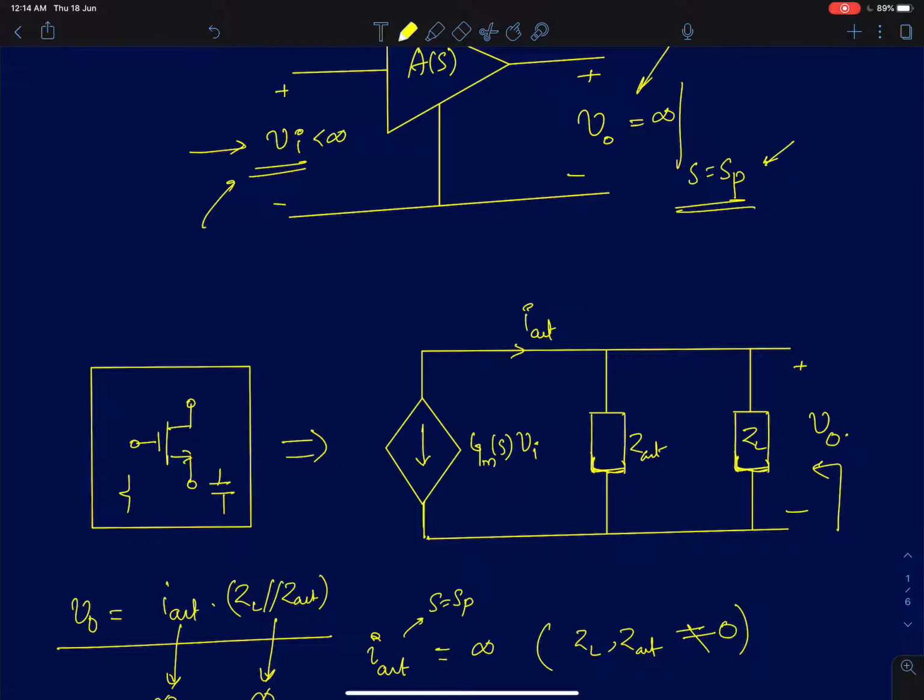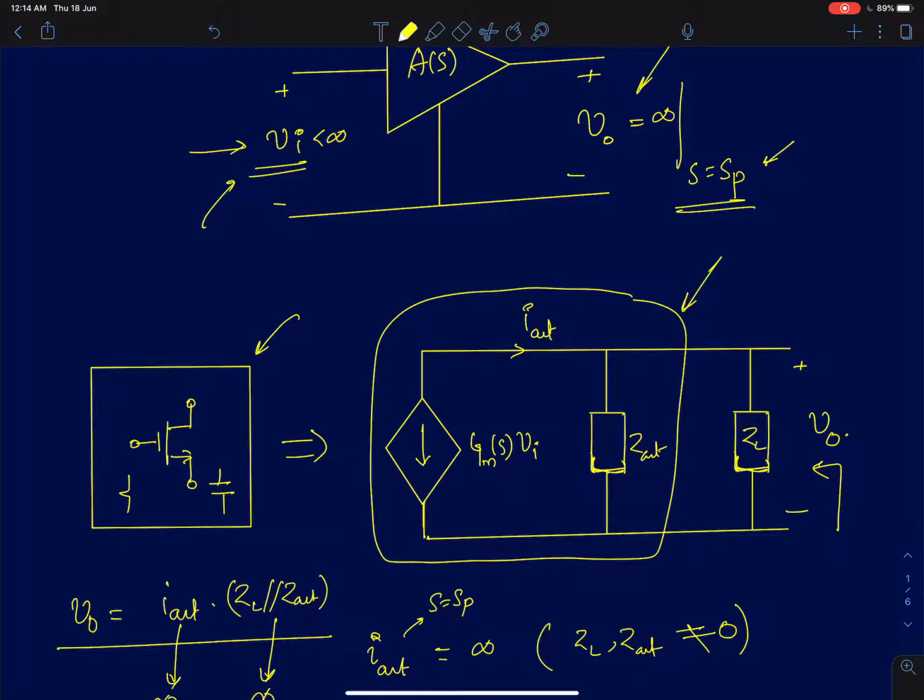First, in a similar way as we discussed in the previous lecture, any MOS amplifier circuit comprising resistors, capacitors, inductors and MOS devices can be represented from the output port by a transconductance amplifier model, as a voltage controlled current source with an impedance Z out in parallel.